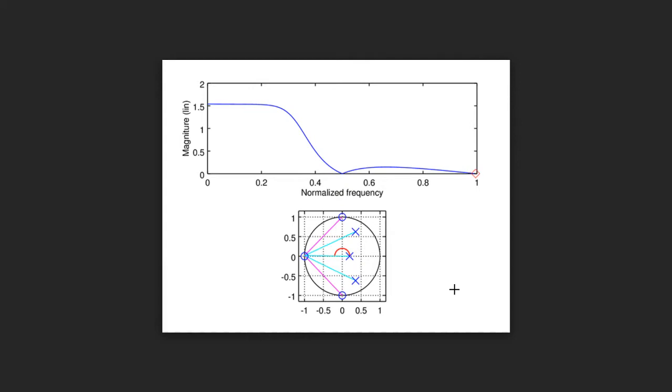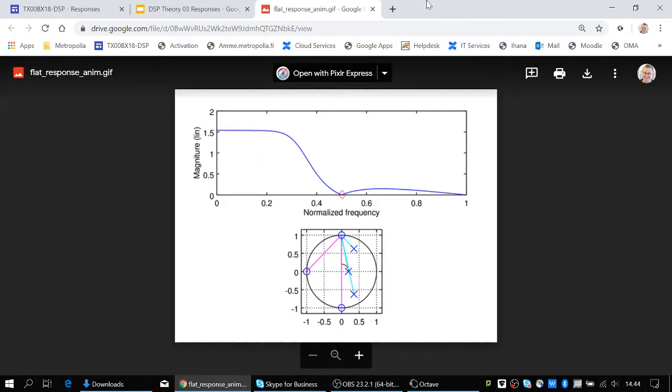So second order Butterworth low pass filter has poles there. Right. Third order, you just have those here, here, and here. Quite similar. They are not anymore actually on the circle, but they are in a kind of elliptic formation there. Good.